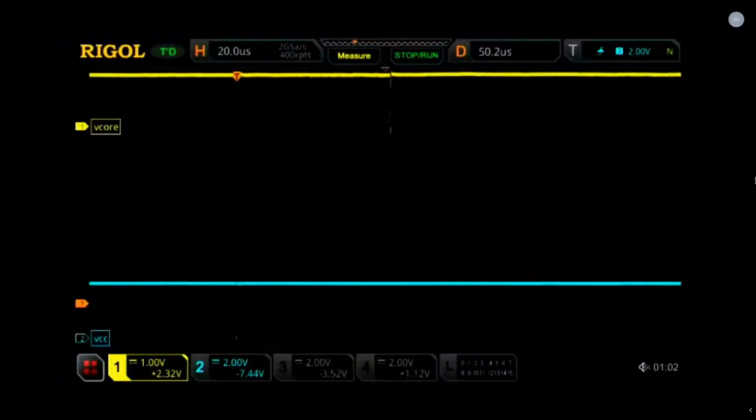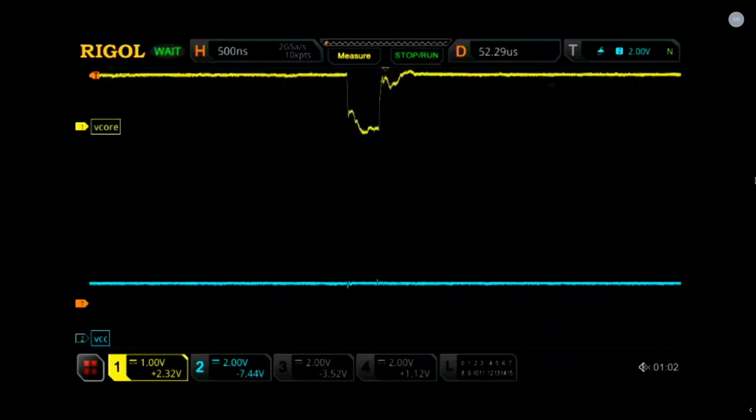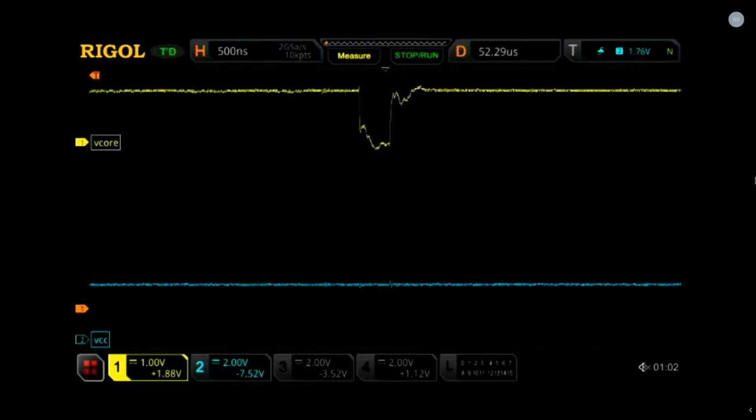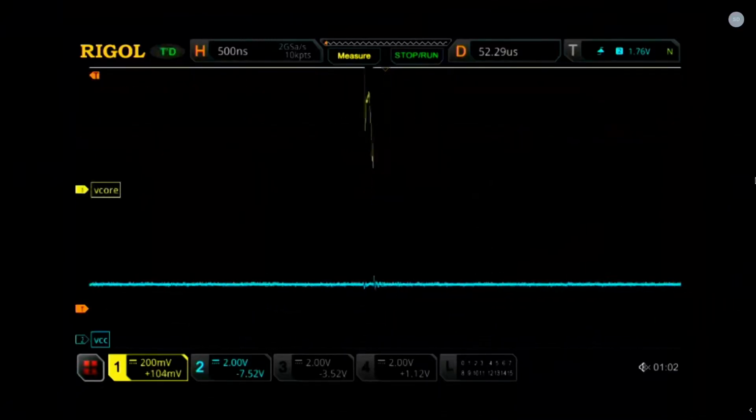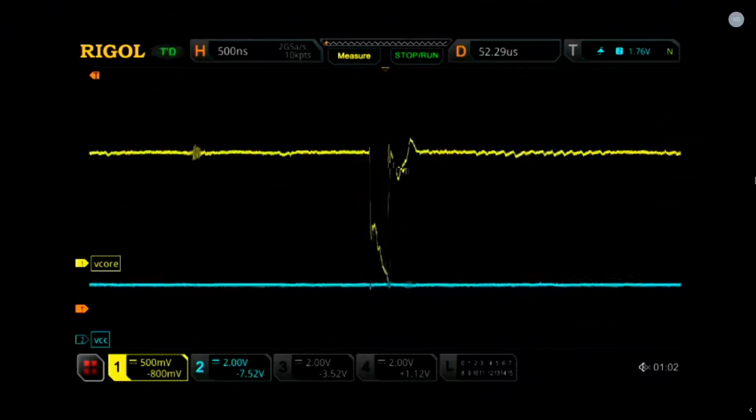And so if you look, the blue signal, you'll see there's a dip, and that's the reset, and this is our actual glitch signal. So you can see right here, what's happening is the board's power cycling, and then we're dipping the voltage at different points in time and just letting it run. And so you can actually see this going across the screen. We can move this guy down a little bit, make it a little bit bigger, just so that everyone can see. So you can see the voltage, it's dipping from approximately 1.6 volts to lower, and we're just going across.